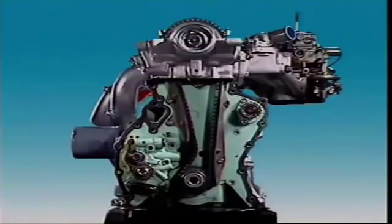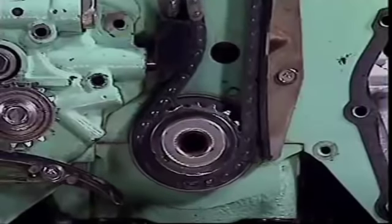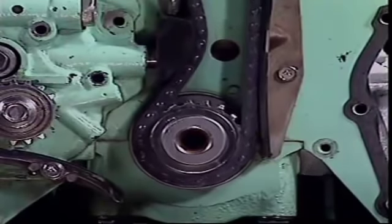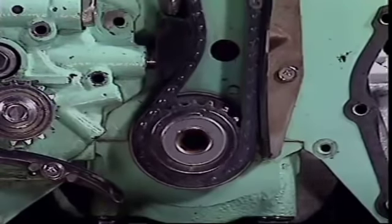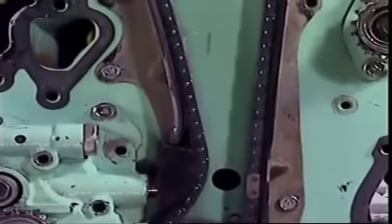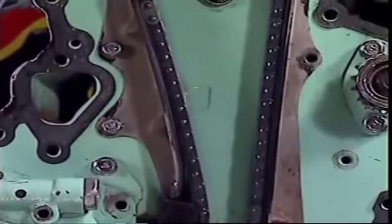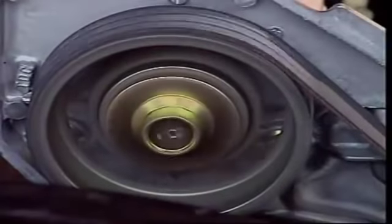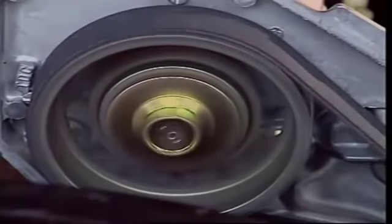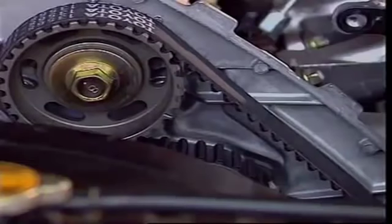This is a typical chain drive system. It uses a hydraulic tensioner which is fed by oil under pressure from the lubrication system. The chain also uses guides to reduce noise and vibration. The toothed timing belt is made of fiberglass or wire-reinforced synthetic rubber. Its teeth match those on the crankshaft and camshaft pulleys.